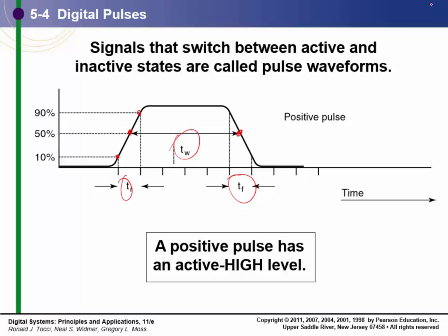Quite often when we're trying to do things like motor control, we'll vary the duty cycle in order to control how much power we turn on a motor or a light or any type of device. For the magnetron on a microwave oven, if you want 90%, you would give it a 90% duty cycle. If you want 100%, you turn it on 100%. If you want 10% power, it'd only be on 10% of the time. And you would vary the pulse width, and that's easily done with a microprocessor timer circuit.